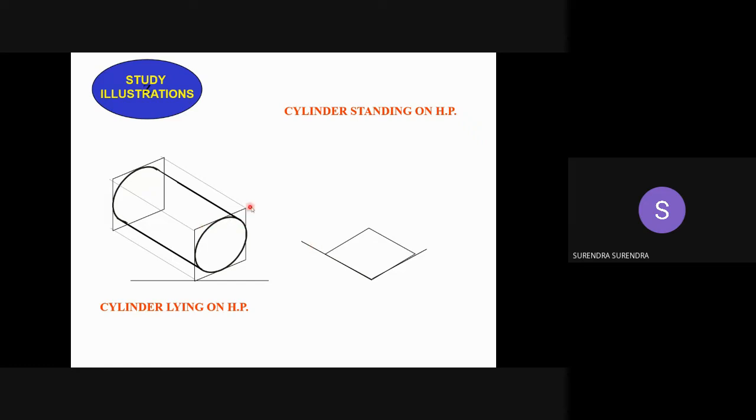Last class we drew how to draw an ellipse in vertical position and horizontal position. So in horizontal position we'll construct the square, and within the rhombus we'll draw the ellipse by the four center method. Now as the axis is perpendicular to the ground, in the vertical direction, from these four corners, draw four lines equal to the height of the axis,